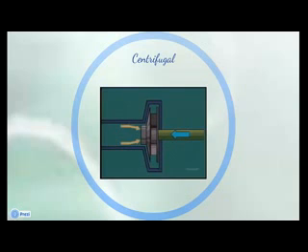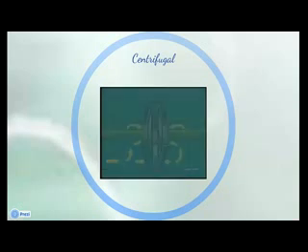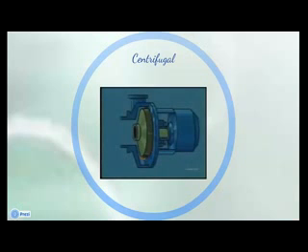It's resolved by using a double suction impeller. This type lets fluid enter both sides of the impeller. That makes the thrust generated on one side of the impeller counter the thrust from the other side. Pumps also come in stages, single or multiple.